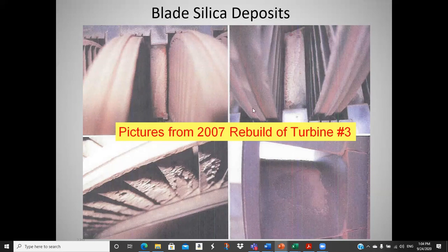And see up here, you see these seals up here. See, there's a stationary... I mean, the turbines open up, but there's a whole row of stationary blades, and then these are the rotating blades in the rotor. And see these little sealing strips up here? These are seals, because if those things get damaged, then instead of going through the blades, the steam can come up around and just go around the stage instead of through the stage. And obviously then that's a leakage path that hurts you.